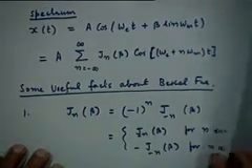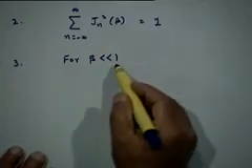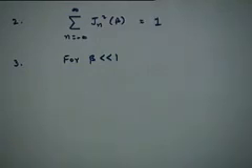So beta is a modulation index, and when the modulation index is very small, that is much less than 1, then all the coefficients that we are referring to, the Bessel functions, have a small argument. We are talking of Jn beta, J0 beta, J1 beta, etc., with beta the argument being much less than 1.